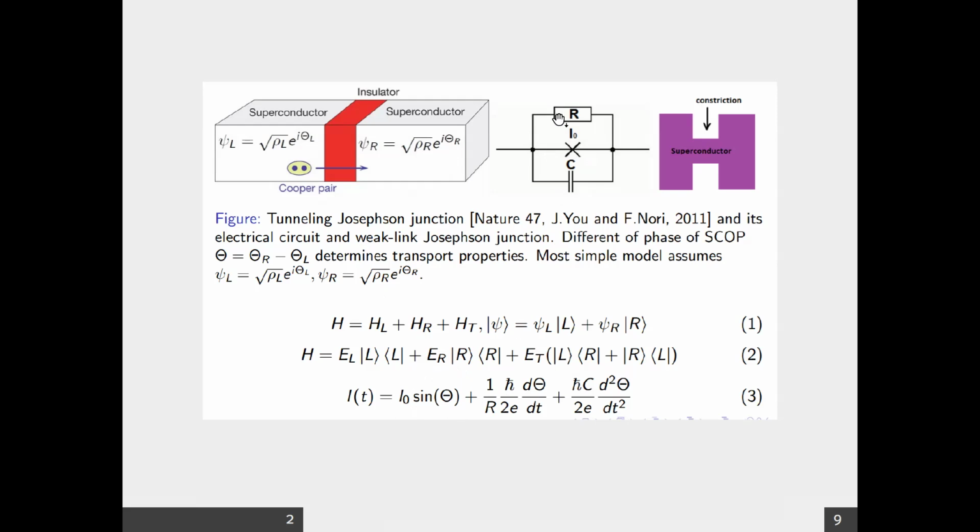And then you have some level of resistance. So Cooper pairs don't generate resistance. Cooper pairs move without friction. So this is like a superconducting superfluid that moves without friction, you can say. And then there is a dissipative current. You will see later why. So this is voltage over R, but in relation to phase difference. So this is the current flowing via this resistor.